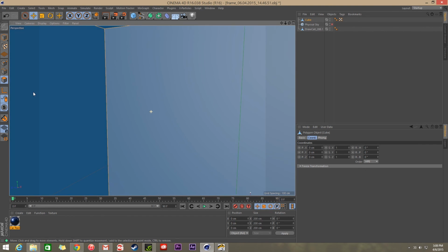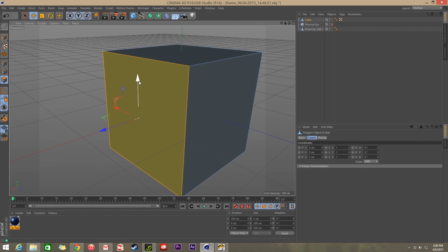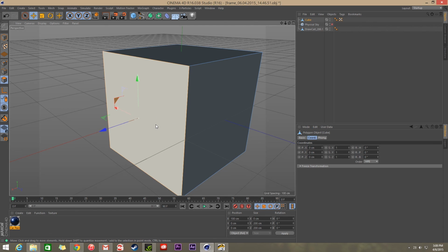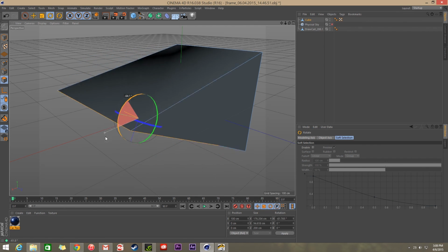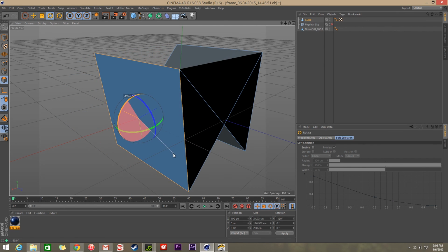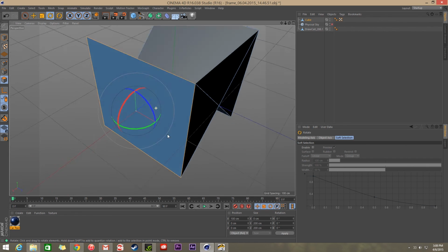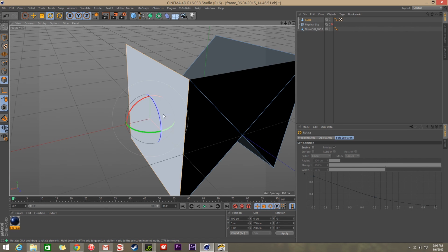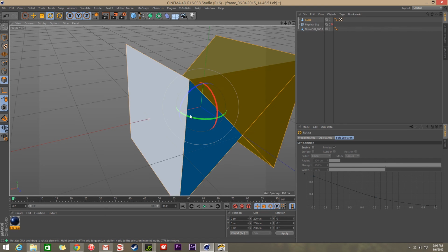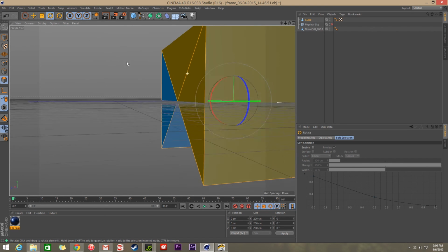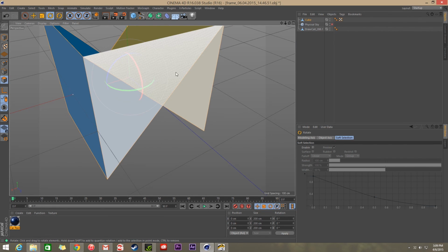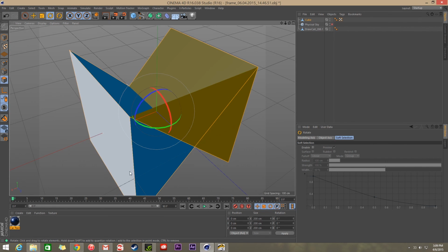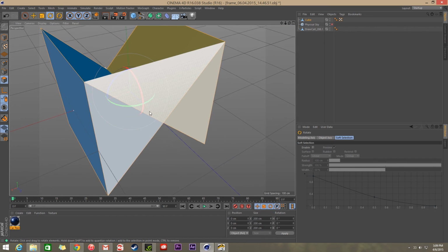But if a normal was flipped, for example, say I'm just going to mess this up on purpose. I'm going to click on this object and rotate this piece around like that. And it's really messing everything up. You can see now that I have a blue normal. This means that this is incorrectly lined up. So if I do Control A, you can see that we're having some trouble here, that this is blue and yellow all here on the same side. So that's not good. That's going to cause a lot of problems and mix up with the textures.